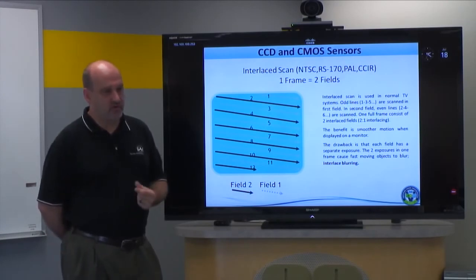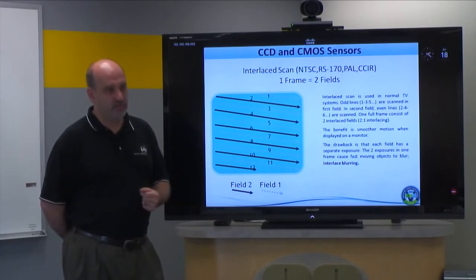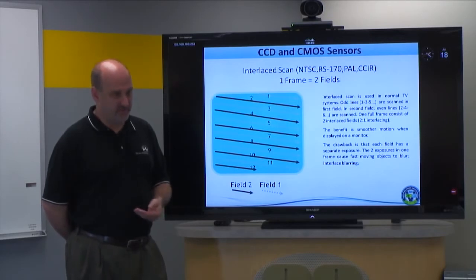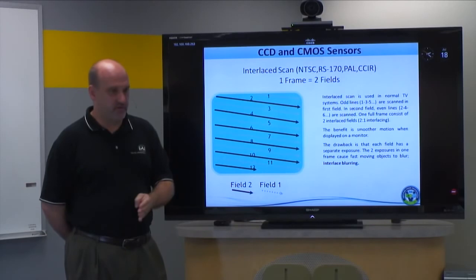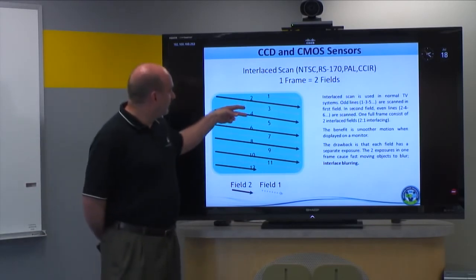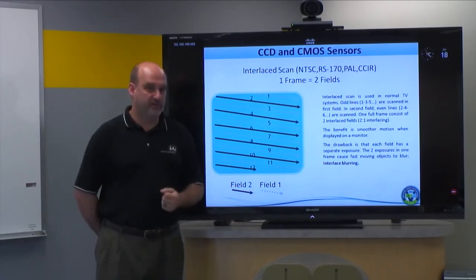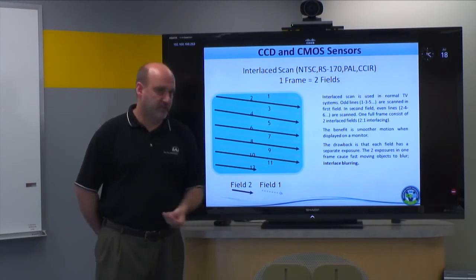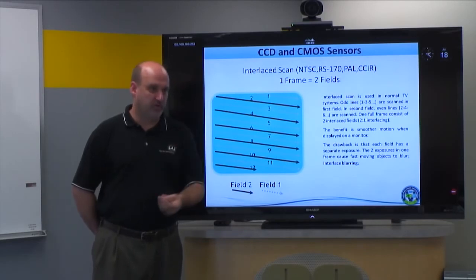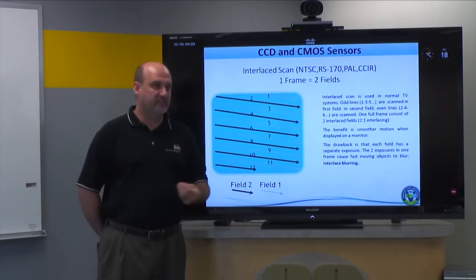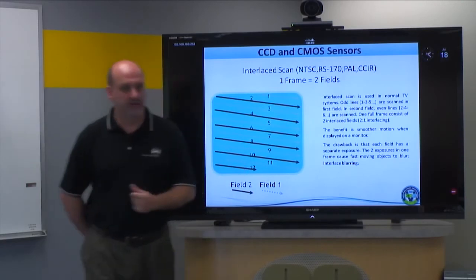But it actually had one advantage. Though the frame rate itself was only 30 hertz, the fields are created at 60 hertz. So when I had high-speed motion, the field nature of this at 60 fields per second let us capture the motion accurately. And because of interlacing two fields at a 60th of a second into a frame at a 30th of a second for watching on TV, our eyes were relatively immune to this, so our eyes could see both the motion and the resolution, even though there was some blurring, and you'll see the blurring occurring.